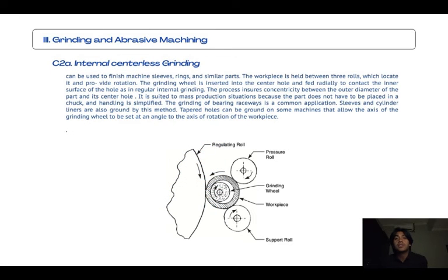Okay, next is vertical spindle surface grinding. It uses a grinding wheel mounted on a vertical spindle with either a rotary or reciprocating table. Various methods are used to move the wheel across the work. The cup-shaped, segmented or cylindrical wheel covers a larger area than the side of the wheel does in a horizontal spindle arrangement, so cross feed of the work table or wheel may not be necessary.